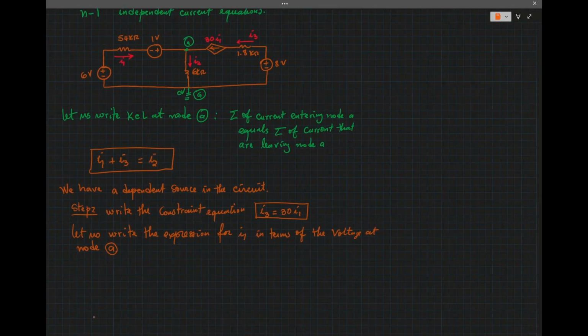We have the 6-volt source, and you agree with me that because the elements are in series, they carry the same current, so I can swap the location of the voltage source and the 54k ohm resistor. Because they're in series, I can rearrange them, and that doesn't change the network.